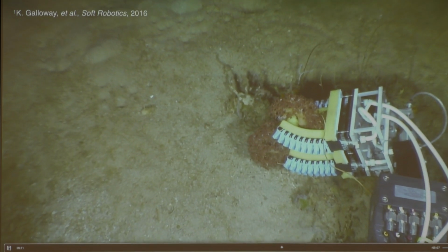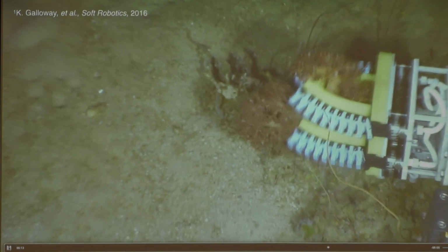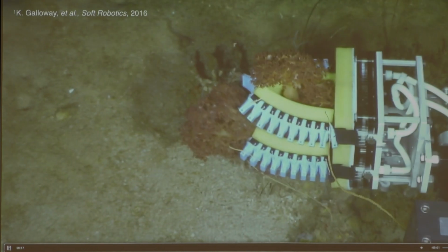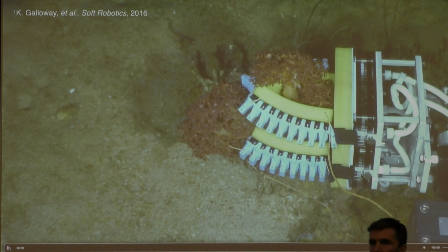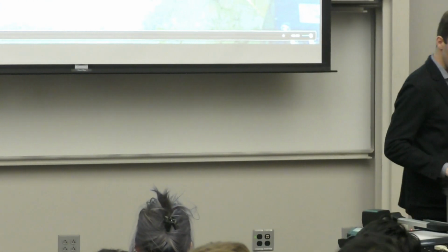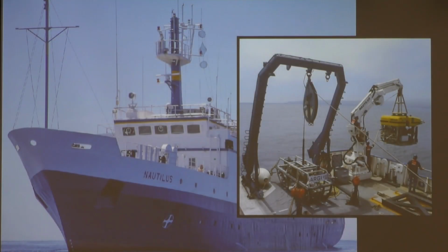There are other aspects of this which I'm not really getting into, but we use an open-celled foam on the palms of these hands, such that we can get some effective force feedback, some effective force control, just by virtue of the materials. The materials have a relatively flat force displacement response, so we can get contact force feedback for free.